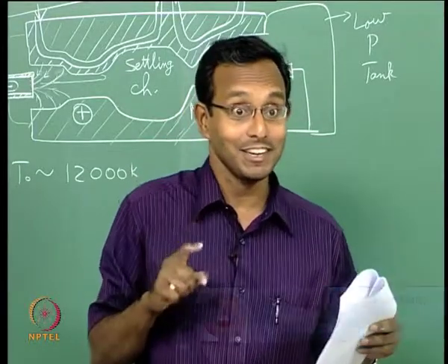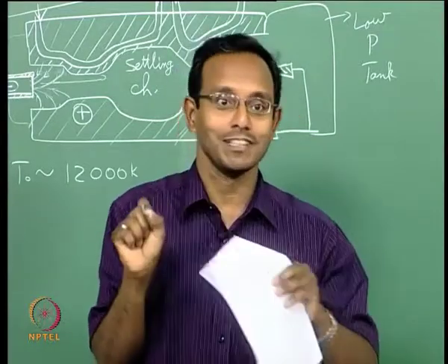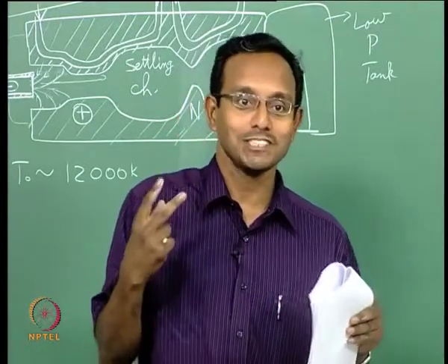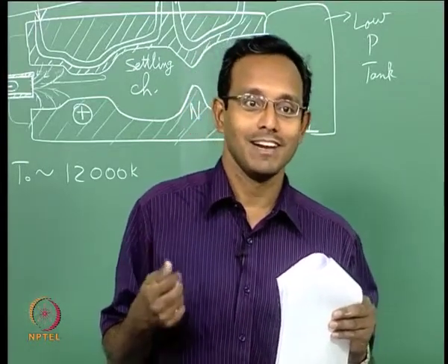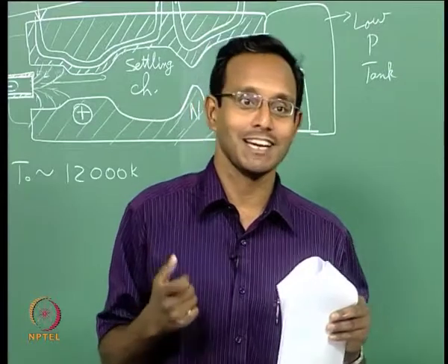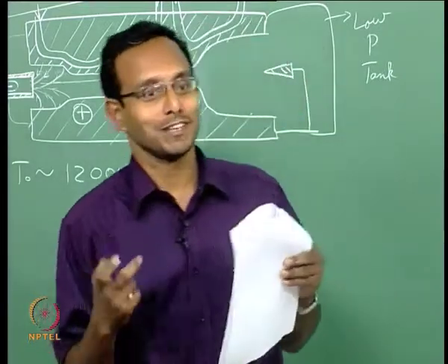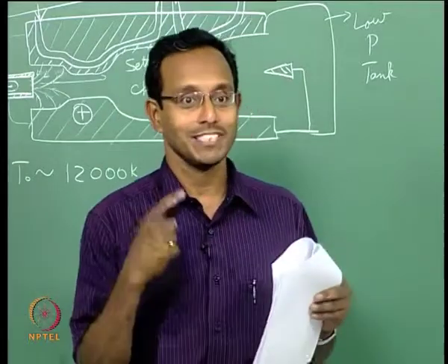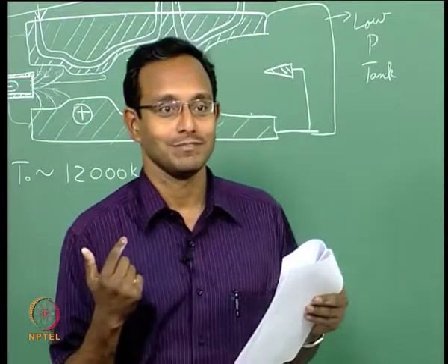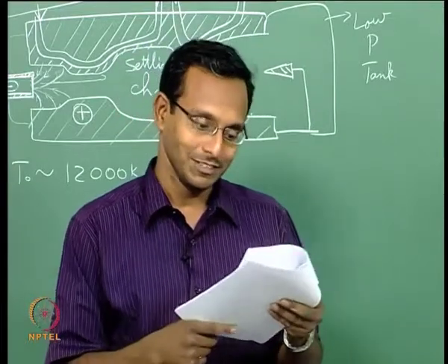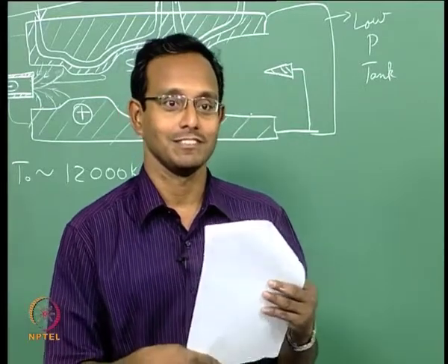Now I am really studying re-entry problem, because now I can put special sensors on that at different locations and actually study the heat transfer. Of course first time I should over design, but later with the sensors I can find out exactly how much is the heat transfer and what could be the pressure distribution, what could be the temperature distribution, etc. And now I can check my whatever insulation tiles, for example. Okay. I can test those things. That is a good thing about re-entry based facilities.